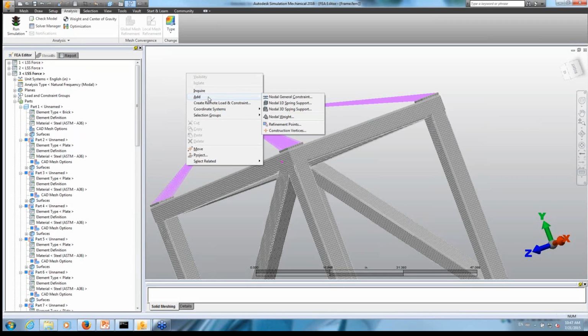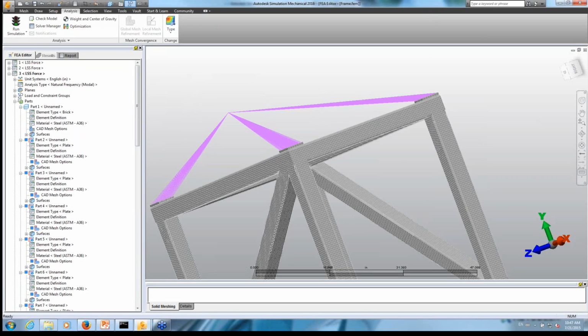But in previous versions of the software, you could. I'm not sure which version that change happened, but previously you could actually apply a force, and unknowingly that force doesn't do anything for you. It has no effect. It was just thrown out by the solver. Effectively, the setup was the same between a natural frequency and a modal with load stiffening, which actually does use those forces. So the setup was identical, but the solver would just ignore them.